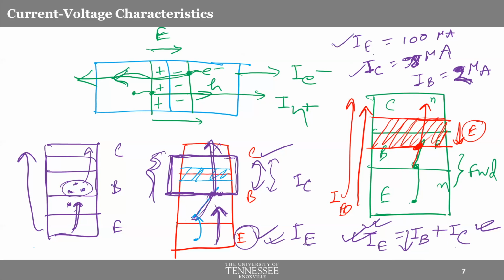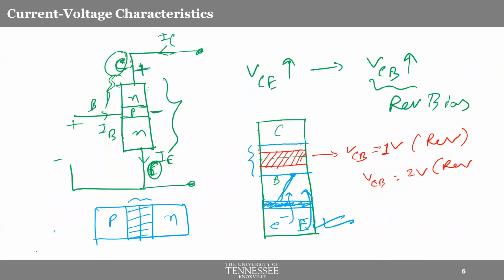to each other. Okay, so when you apply a stronger reverse bias at the base collector junction, that actually helps transfer of electrons from emitter to the collector. I hope that makes sense, that that eventually reduces the base current. Remember, you are talking about the base current in the input characteristics.